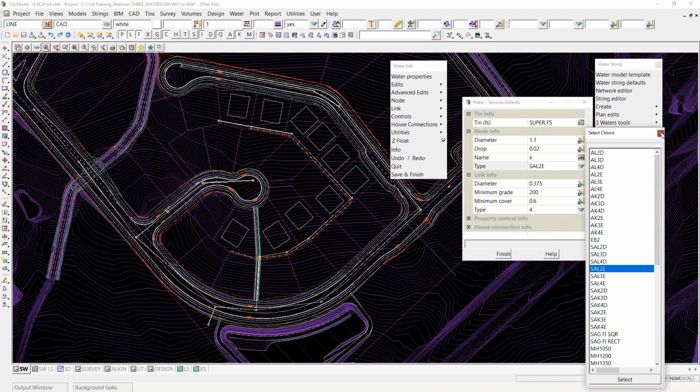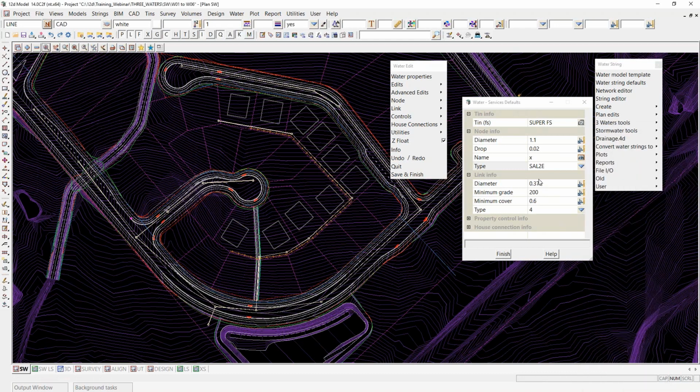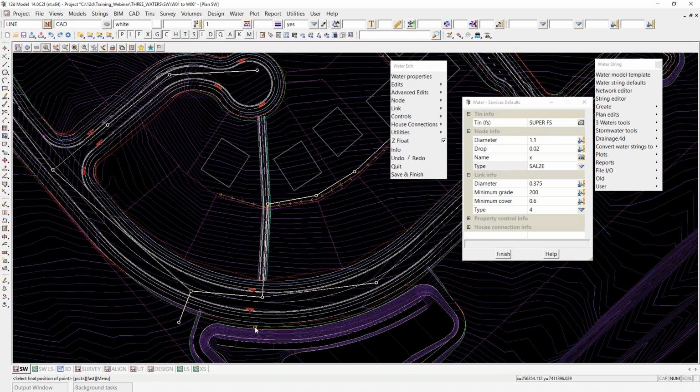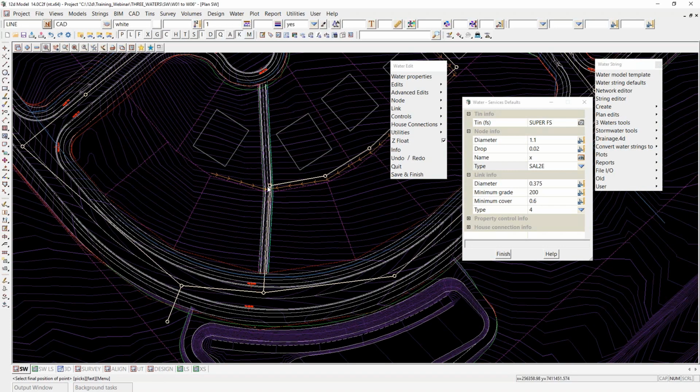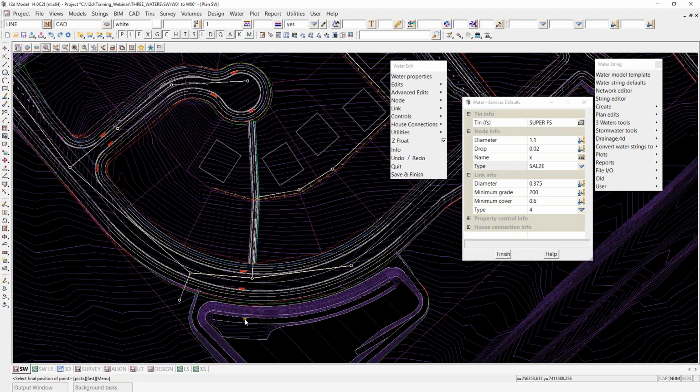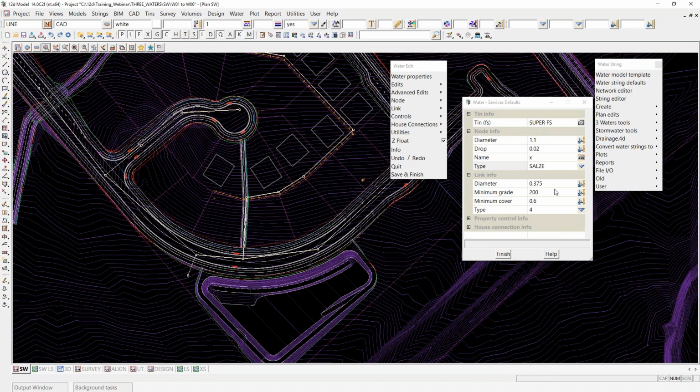Okay, so we set all that up in episode 1, and in fact, I do want to leave it as this SAG node because the first line I'm going to create, I'm going to define a line from the SAG that I've got in my cul-de-sac here, working down this easement, and there's a swale built in this easement here, picking up 2 sags along the way. I'm also going to pick up this roof drainage system that I described earlier, which I haven't even got as water strings yet. They're just these CAD strings or super strings, and ultimately discharge all of this out to my stormwater basin here somewhere. That'll be my discharge point into the basin. Okay, so that's the plan.